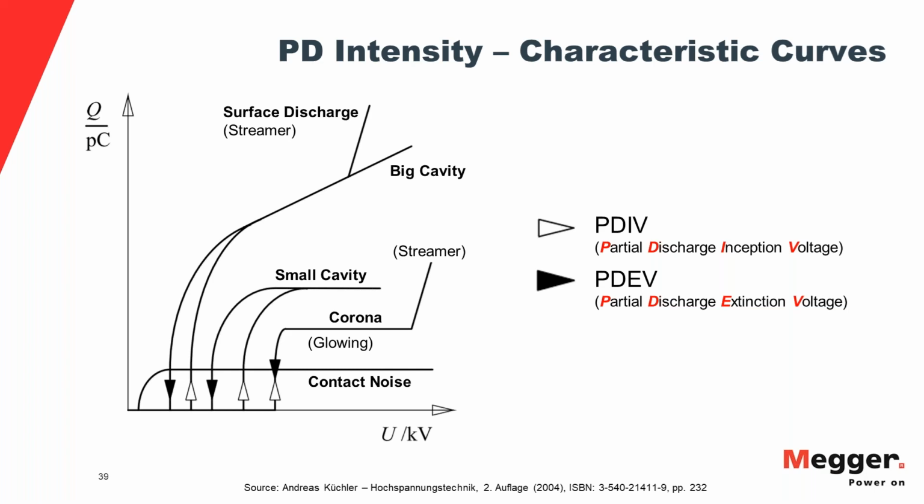So it's less, and it can be 10% less up to 30% less. That's the extreme numbers that you see. So rule of thumb, you can say 80% of IV typically, with exceptions. It's just an idea. It's not exact. So you start the event, or the partial discharge is being ignited, and it goes out at 80%.